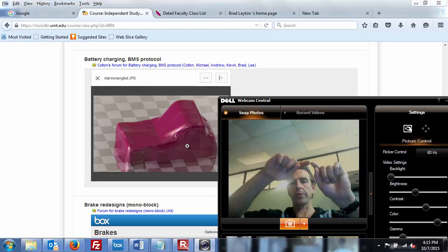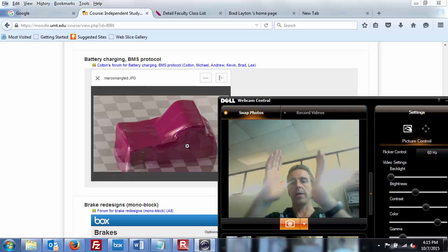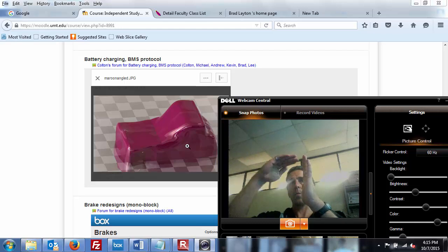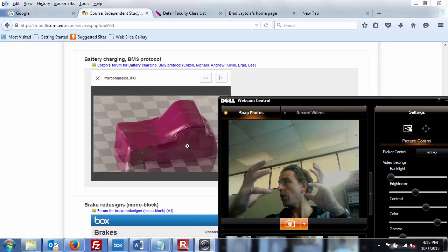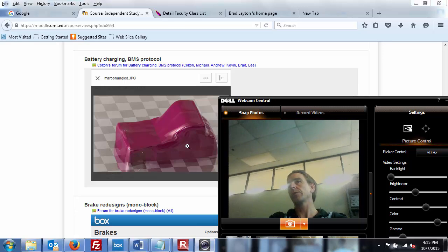You cut those ribs out with your milling machine, and then stick the ribs together every 4 inches, and in between you sandwich the foam. Then you can use the edge of the wood with a hot wire to remove the excess foam, and now you've got an actual solid piece, and then you can lay the fiberglass and whatnot over that. It works pretty well.